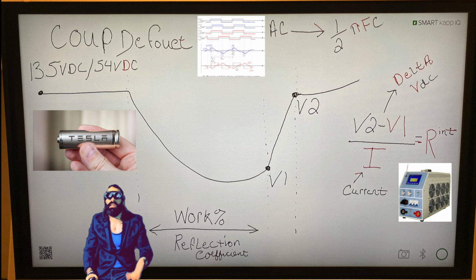Now, I'm not talking about spectroscopy here, which I fervently believe in, because that is inserting several different frequencies across the anode, the cathode, and the material science of the battery system. I think that's probably something we should be using moving forward, because it's going to catch a lot of other failure mechanisms. But AC impedance and conductance, in my opinion, generally only finds certain types of battery failures, or a battery that is now open. It's not going to find a degraded battery over time.